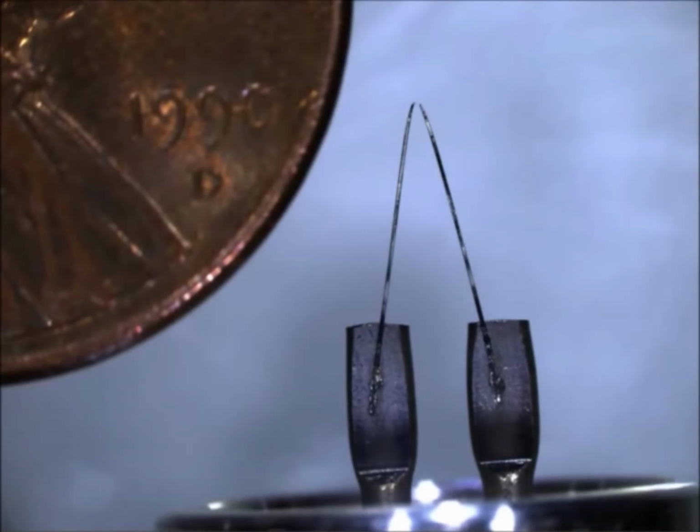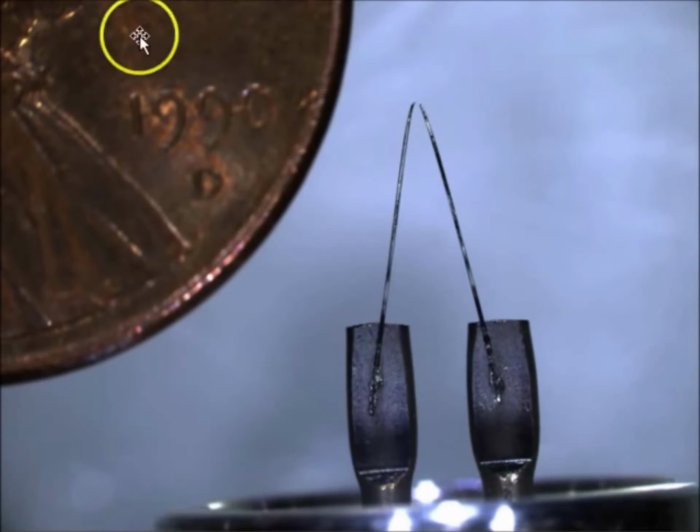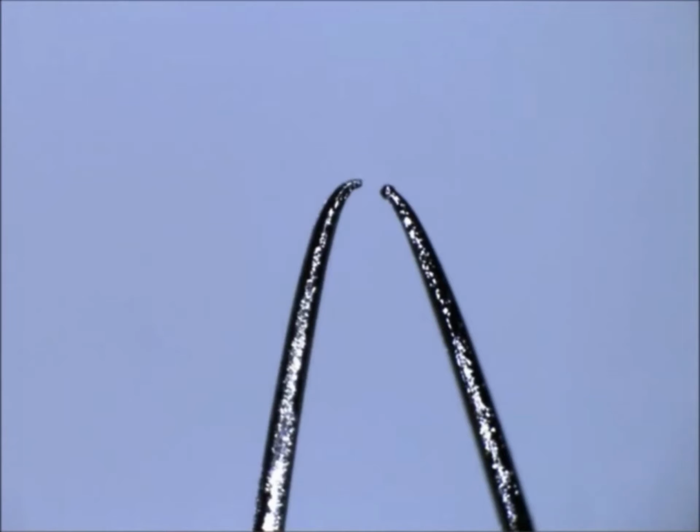Here's a photograph of the electron gun taken with the Leica dissecting microscope. This is called a thermionic electron gun, which basically means we're going to heat it up, and it's going to give off a bunch of electrons. To give you some idea of the scale here, this is just a penny I had in my pocket. I stuck it down there with it so you could see what's going on. By the way, just to show you a nice image from the Leica here, you can see that this filament's actually burned out. So this wears away as we use it. We put 15,000 volts through there, or on the big scope we'll put up to 30,000 volts through this filament, and it eventually burns away.